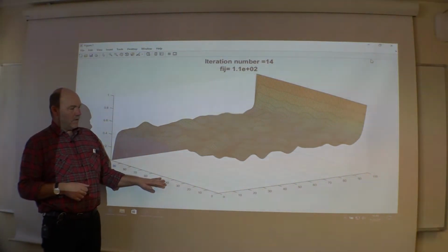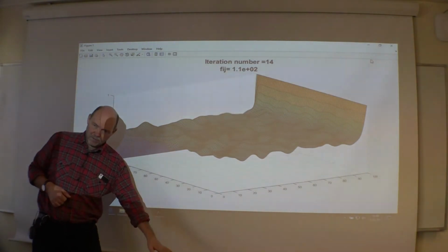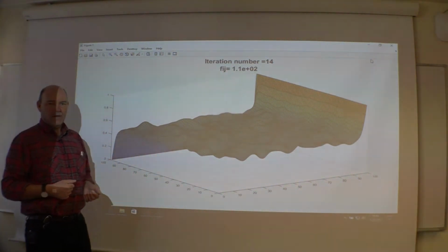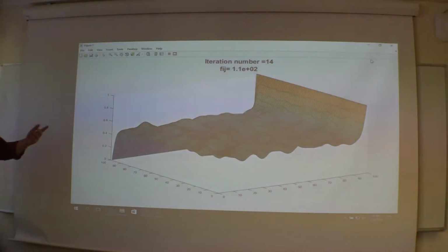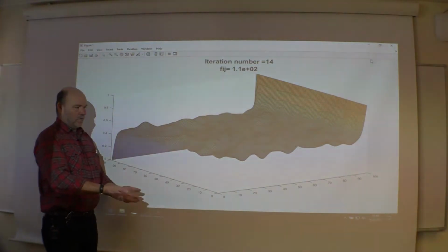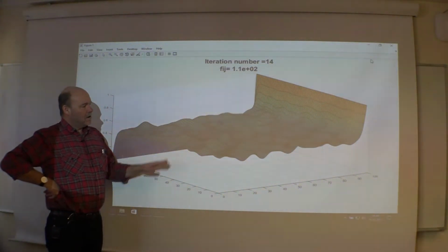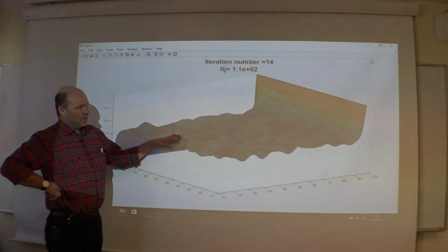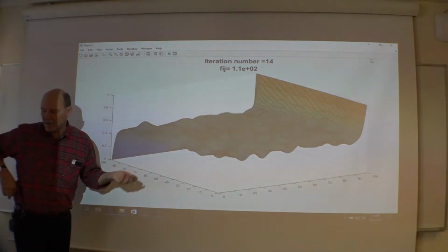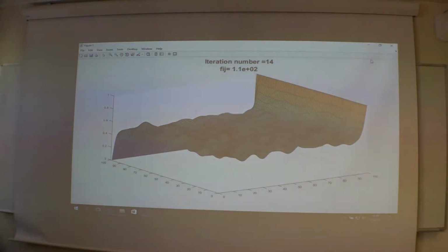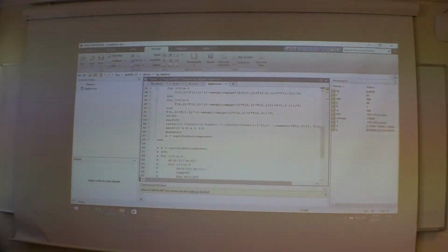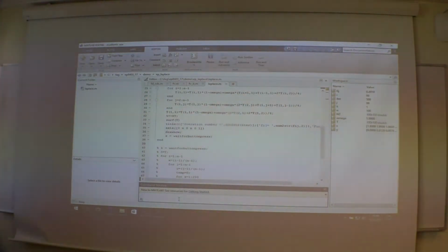And then you could actually transfer it to an even coarser mesh. You can have several mesh layers, coarser and coarser, and then use the same idea. Sooner or later, when you have the solution, you have to nest your way back up again to the finest mesh to obtain the solution on the fine mesh. Of course, that's what we want in the end. But the idea with multigrid is just that. Take benefit from what these classical methods are good at.